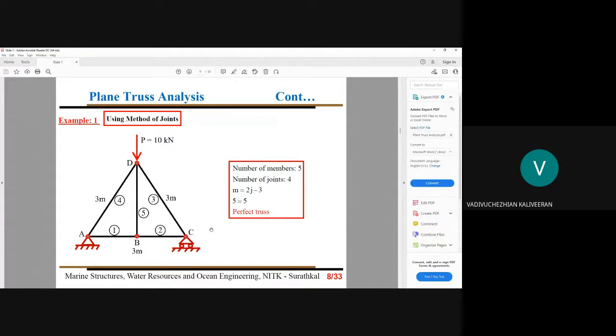We have force equilibrium along the x direction equal to 0. That way, we can eliminate this horizontal reaction. With force equilibrium along the vertical direction, we keep one more equation, that is V1 plus V2 equal to our applied load. And we will also use moment equilibrium with respect to A to take care of our support reactions, not joints. So now it is possible for you to fix your number of unknown reactions in this problem.